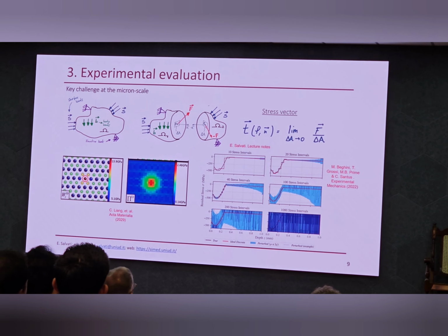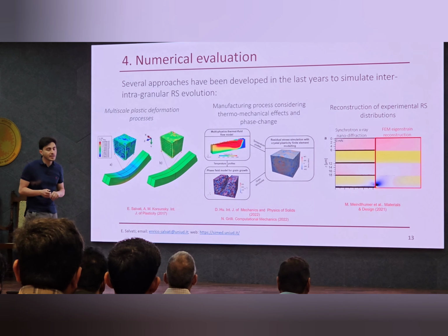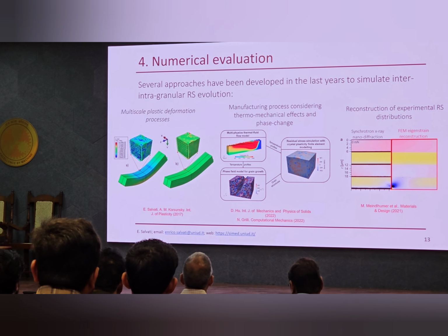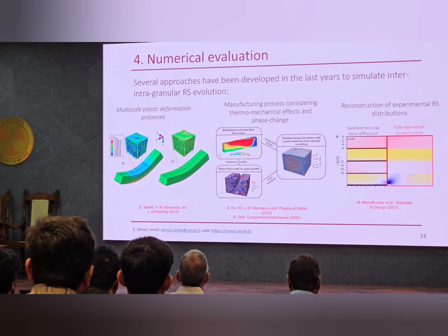It's called the eigenstrain reconstruction method, and basically this method allows you to enforce the information of the residual stress that you get experimentally by constraining using the balance and the compatibility. Okay, you enforce these experimentally evaluated values and distributions so that you can check whether you're doing it right. And this is particularly useful when you deal with non-destructive methods, where you don't know the absolute value, but by introducing the eigenstrain concept, it's very helpful to get reliable results.